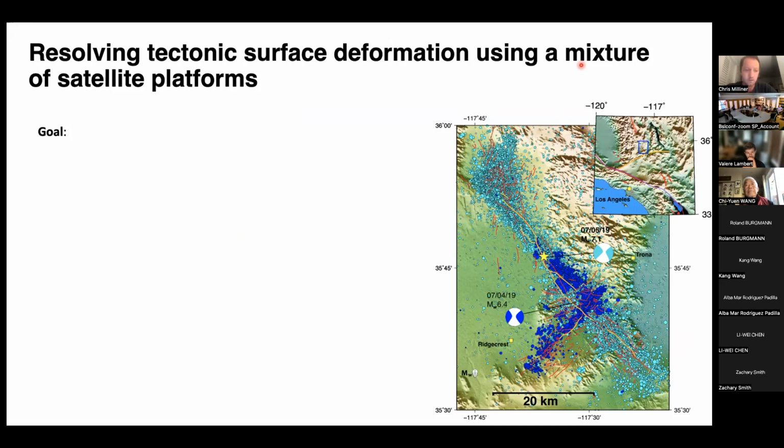Right. So really, you want a range in the look orientation. Our images typically span about 20-30 degrees difference in the look directions. If you can improve upon that, you'll have a more accurate estimate of the vertical component of motion. If you don't have a large range in the look direction, you won't have a very precise estimate of the vertical component of motion. So you can still get the 2D component, just the vertical won't be as accurate.